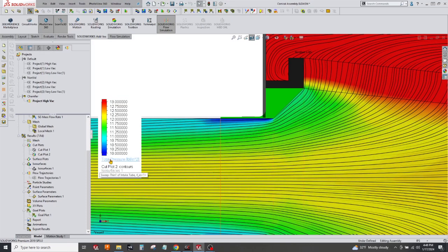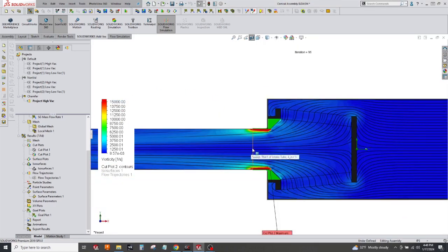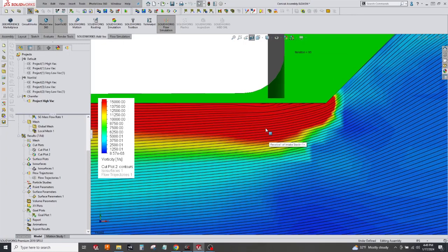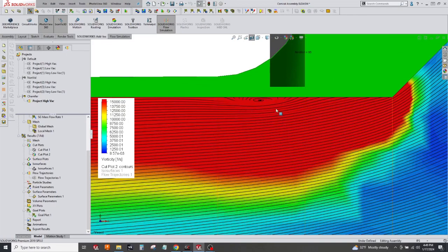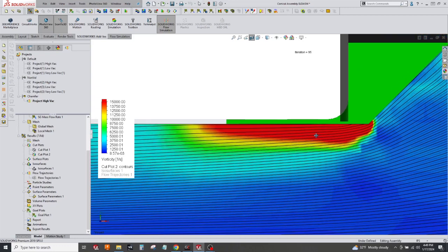Well, this is total pressure. Let's go ahead and look at vortices, just because that's what we were last looking at. Oh, good. We're already set to 1500. Well, is it as good as the fillet? No. But I don't see any massive... There's a little turbulence in there, like actual flow lines shifting around. And we do have a little bit more red region in the vortices, but let's take a look at some actual numbers.